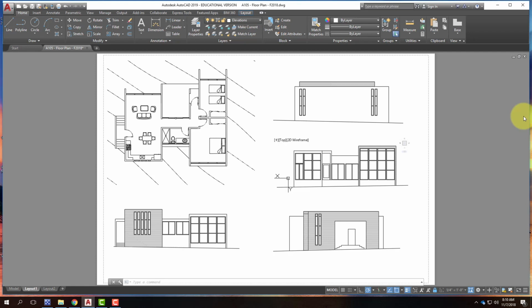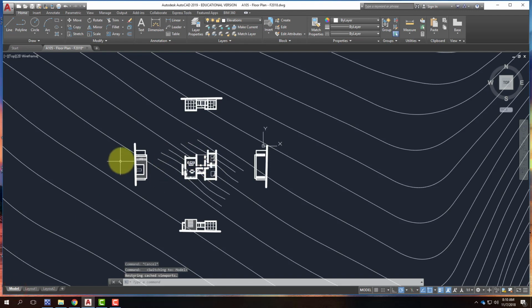And so today we have our drawing set up in Modelspace. Hopefully you've gotten to the point where you have your floor plan and your 4 elevations. If you don't have all 4 elevations, you could spend a little bit more time today working on those elevations. But I want to make sure you understand the concept of Paperspace and Modelspace. So we're going to do the layout regardless today of whether or not you're done with all the elevations. So as we get started in this world, we're going to switch from Modelspace into Paperspace, and then we're going to create our page size in the first place.